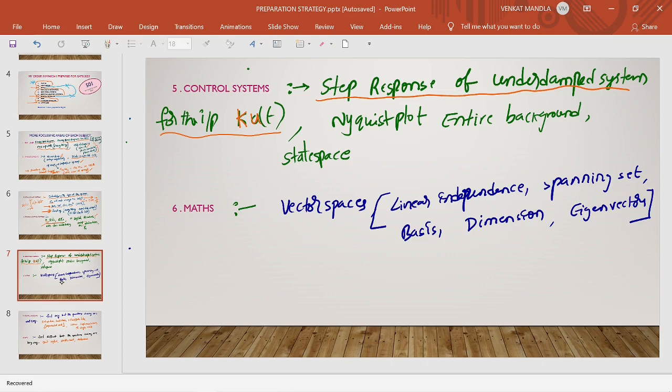Mostly you won't get any change in any specifications, but only one specification will change, that is the maximum peak overshoot. Maximum peak overshoot will be k times the initial maximum peak overshoot when we apply only the step input. But the percentage will not change. Percentage of maximum peak overshoot will not change, but only the maximum peak overshoot will change. Keep that in your mind.